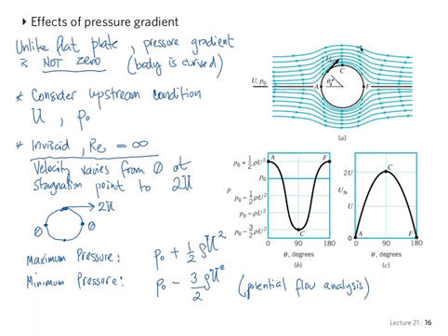We don't impose no-slip. We do have to impose the no-through boundary condition. The vertical component of velocity at the boundary has to be 0, because it's an impermeable boundary. So the flow has to adapt somehow and go around the object. It's an obstacle. But the way it goes around is with slip, and so it recovers completely and the streamlines are symmetrical. That's the case of inviscid flow.